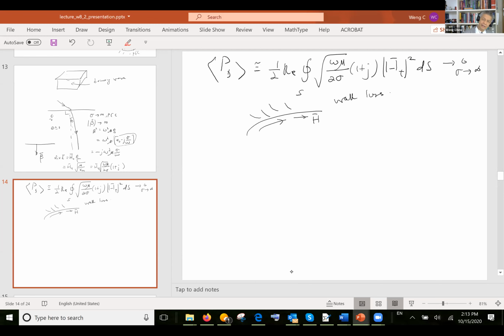You can take the magnetic field of the cavity before you introduce wall loss and use that to estimate this number. Then you will have a good estimate of PD, and then of course WT you can find by using twice the energy of the storage in the magnetic field. It should be the sum of the electric field and the magnetic field, but for a resonating cavity, those two are equal to each other, just like the energy of a tank circuit.